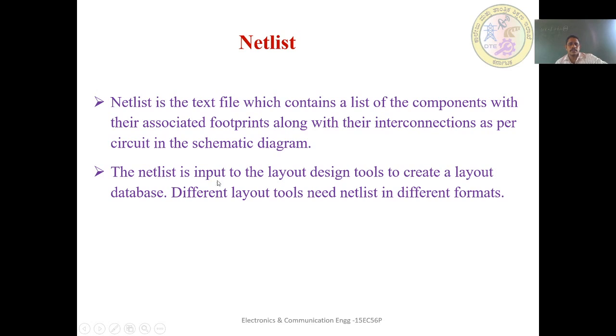The netlist is input to the layout design tools to create a layout database. Different layout tools need netlist in different formats. The netlist is also useful for testing the PCB, and whether the schematic capture as done by the layout engineer is correct or wrong can be checked by using the netlist.